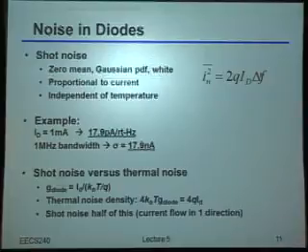Okay? Now notice this is very different than thermal noise was, because we said that in thermal noise, the current didn't matter at all, right? The thermal noise was totally independent of what you did, for example, to the resistor. Here it's directly proportional to how much current you have in the first place. And interestingly enough, it's also related to the electronic charge. So, anybody have an idea of where shot noise is actually coming from? How the heck did the electron charge come into the picture here?